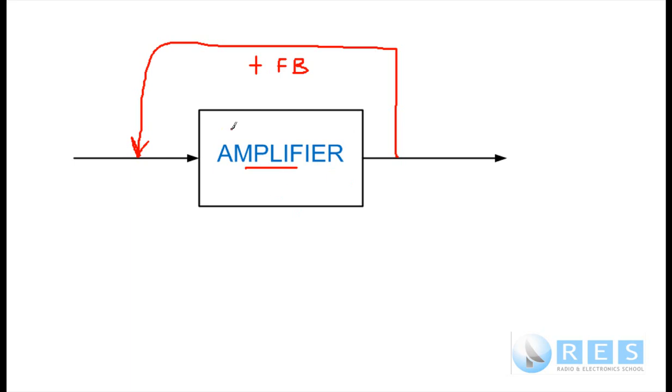Where will the amplifier oscillate? If we want the oscillator to oscillate on 7 megahertz or 10 megahertz, we need some device in the amplifier to determine the frequency of oscillation. Normally, one of the things most often used is a tuned circuit, a parallel or series tuned circuit, because that will determine the frequency of oscillation. We need a frequency determining device. Amplification, positive feedback and a frequency determining device are the three requirements for oscillation, and you need to know that.